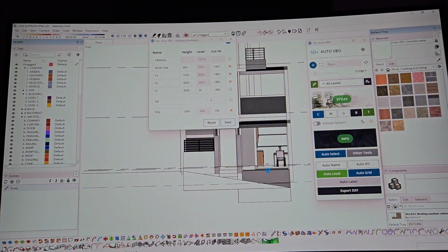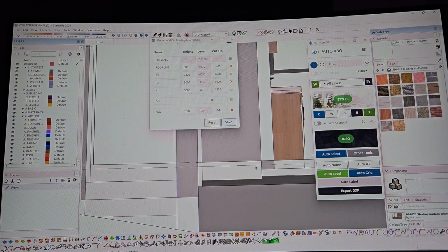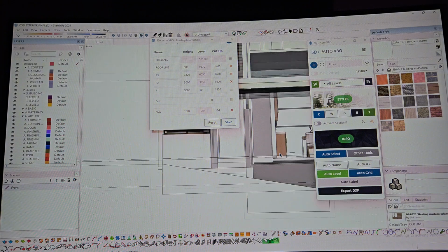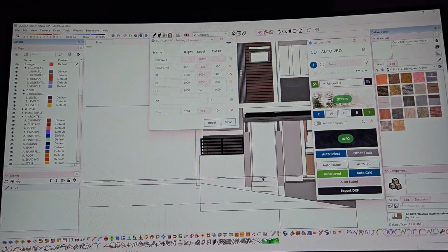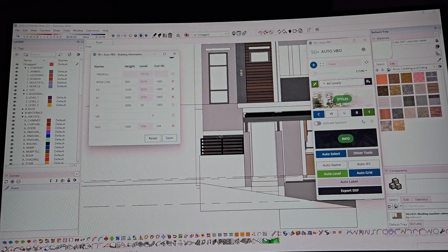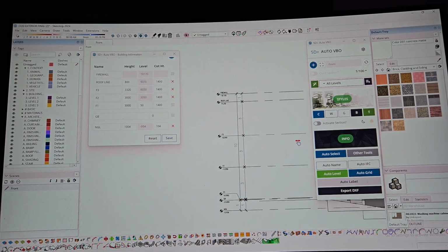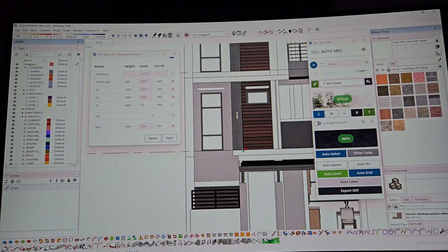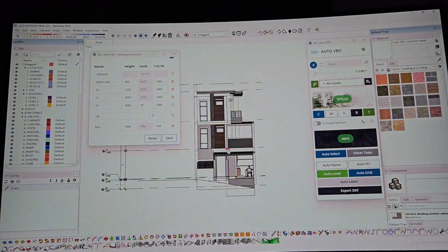Okay. So actually we have to fix the model when we go to the structural that this is the top of the grade beam because this is the floor finish. Right. It makes it kind of hard because every floor finish inside is actually elevated by 5 cm. But it makes it also harder outside if we call this the finish line because this is actually easier to do during structural works.